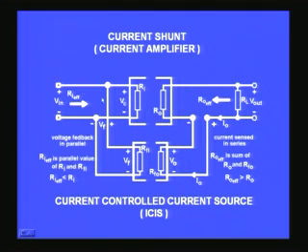Therefore you can see when I have two parallel resistors, if I look at the effective resistance at the input side, it is the parallel combination of Ri and Rf. This is the input resistance Ri and Rf, the feedback resistor. Any parallel resistance will have the effect of reducing the effective resistance, and therefore the input resistance has now effectively decreased due to the parallel combination, due to the type of feedback that I have given at the input. At the output, because the two resistors come in series, the effective resistance is increased with reference to R0. So this is what you should understand. The input resistance decreases, the output resistance increases.